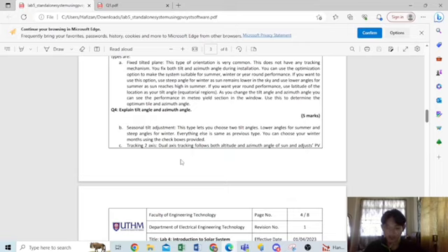The azimuth angle refers to the orientation of the solar panel with respect to true south. The azimuth angle is measured in degrees clockwise from the south. The ideal azimuth depends on the location and the season. Proper adjustment of the tilt angle and azimuth angle of the solar panel can increase its efficiency and improve the overall performance of the solar system. These angles can be calculated using various tools such as a solar calculator or with the help of a professional installer.